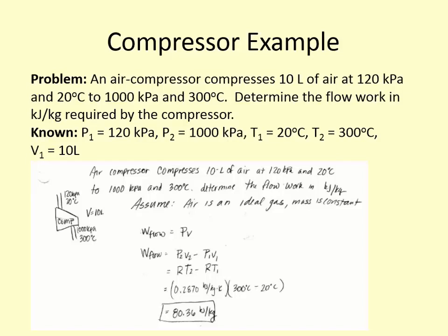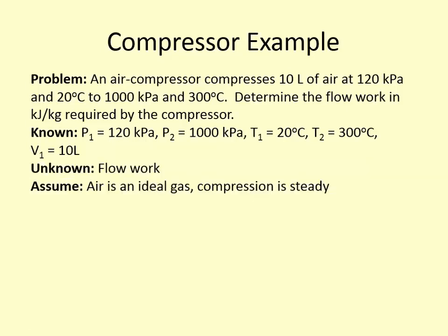Okay, so the difference is in the problem you have to do for homework, and that problem is 21. So you're given some information about it. Refrigerant 134A enters the compressor of a refrigeration system as a saturated vapor at 0.14 megapascals. So what's your state 1 in the homework problem? At 0.14 megapascals saturated vapor, are you given enough information to fix the state?